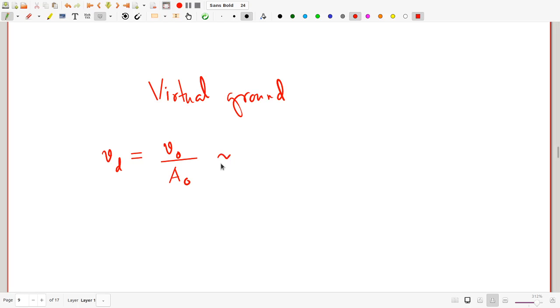And because the open loop gain is so huge and the output voltage is limited to within plus minus Vsat, this must be nearly 0. And that implies that the two differential inputs of the op-amp must be at almost the same voltage. In fact, the difference between the two voltages is expected to be so small for most op-amps, in fact for all op-amps, that you can safely neglect the difference.